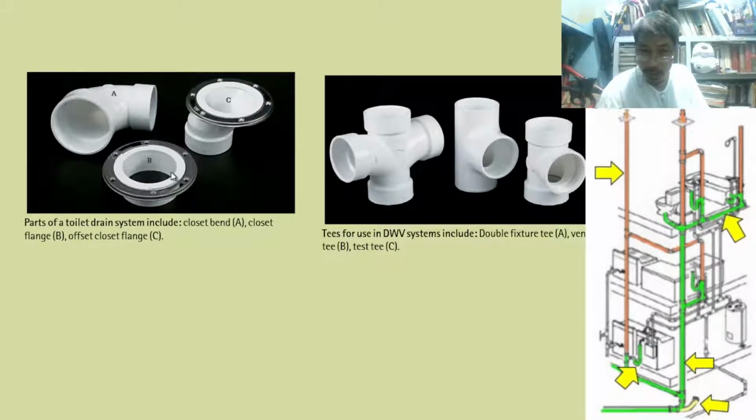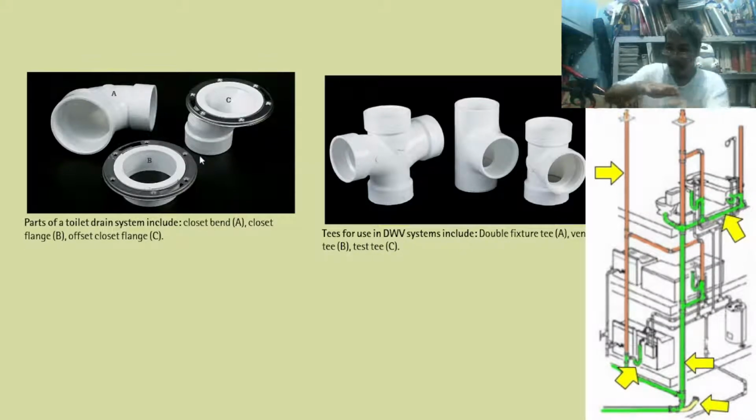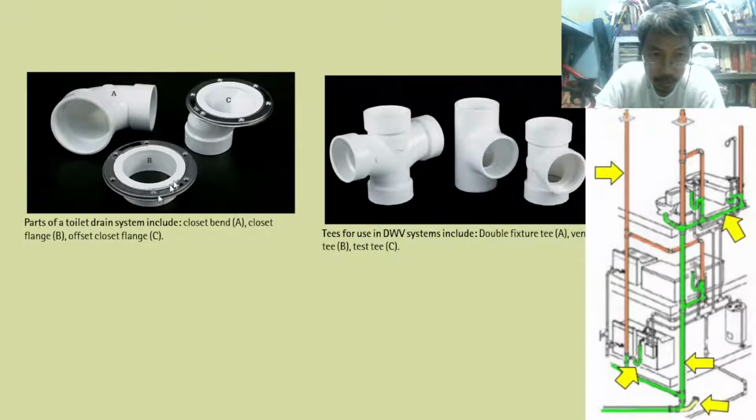Okay? You have to connect it by what? By seal and cement paste. And you have to fix this to the concrete by using pins or bolts here. There are bolt holes here. And then at the bottom, the lower part, you have to put this 4 inches. This is standard 4, and then a reducer, this will become 3 inches here.